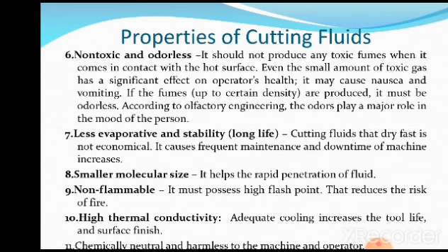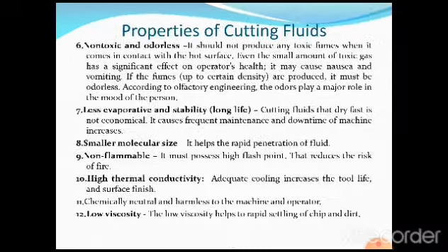High thermal conductivity. Adequate cooling increases the tool life and surface finish. It should have the property of conducting heat. Means it should have high thermal conductivity without getting heated very fast, because that will increase the tool life as well as improve the surface finish.